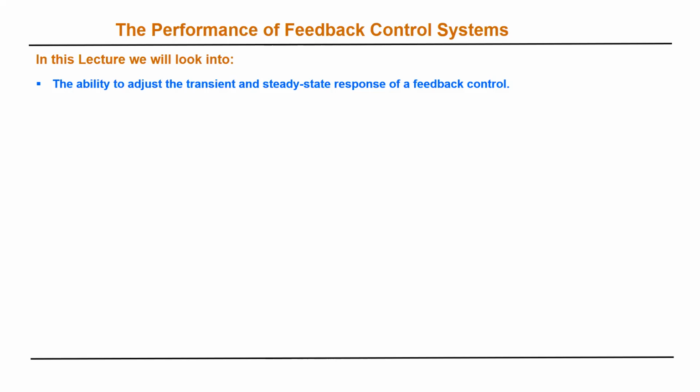But what I'm trying to say here is that you should understand in the time domain, steady state means you let the time go to infinity. If your system is stable, you reach a certain level. If the system is unstable, then your response will be unbounded and there is no steady state. You don't reach steady state. So steady state is associated with stability.